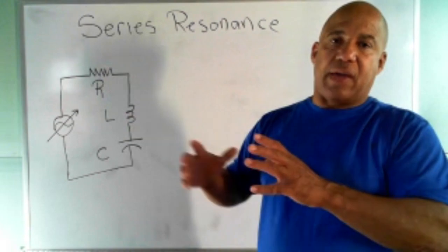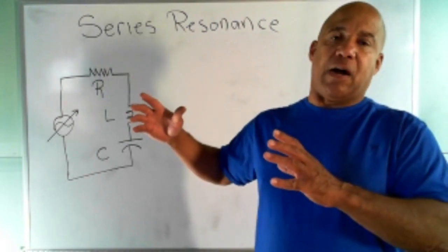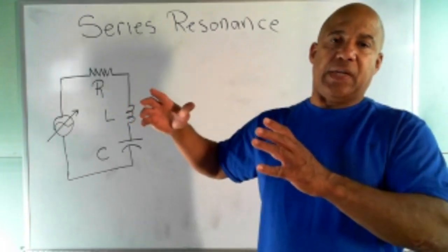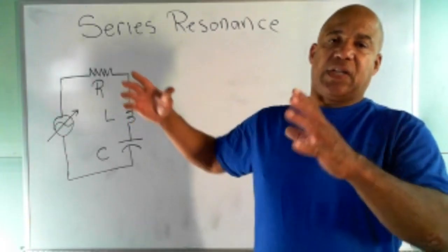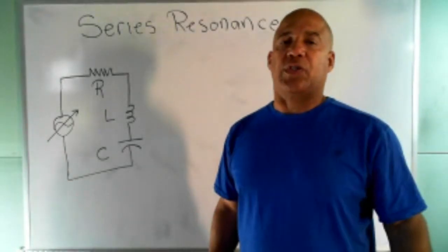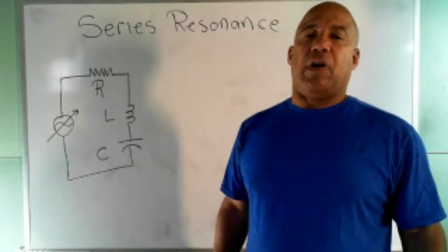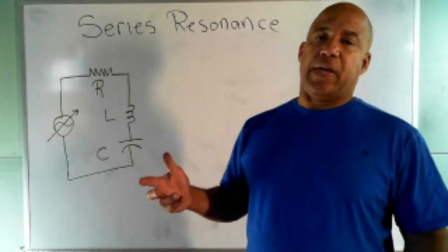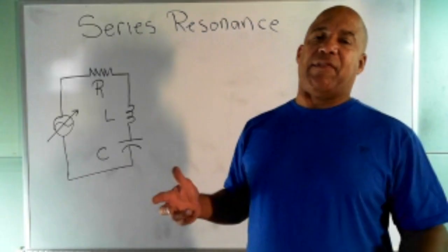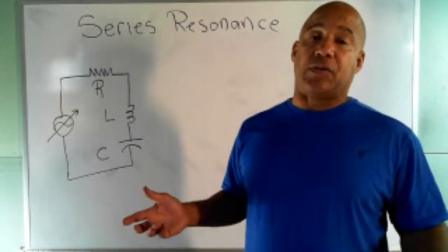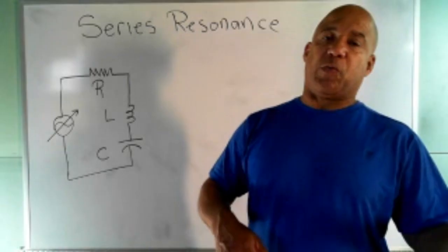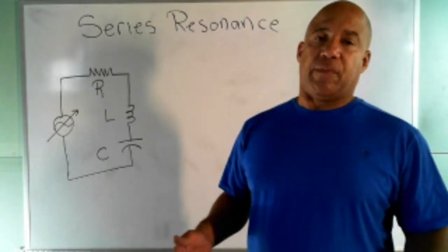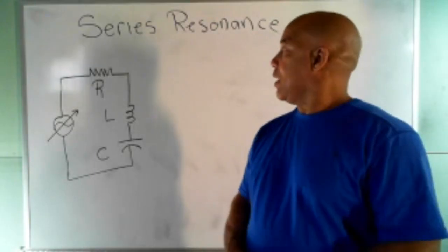While it's collapsing, you have Faraday's law. You have a magnetic field, you have a conductor, that will be the inductor, the coil, and the field is collapsing, so you have everything you need to induce a voltage, and since you have a closed circuit, a current will flow, and that current will flow into the capacitor and charge the capacitor back up. As long as I have ideal capacitors and inductors, I never get any power loss. So the energy just goes back and forth between the capacitor and the inductor, and it does that at a certain frequency. So that's one thing we learned.